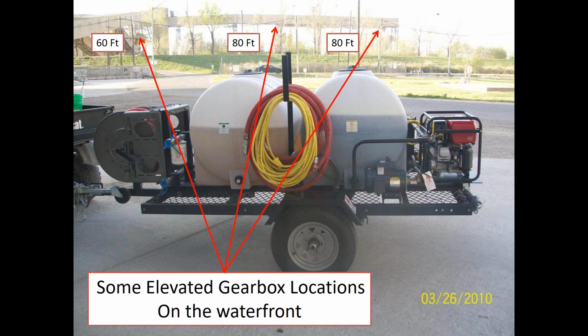This is a cart at a grain elevator. We built this trailer. It's got a dirty oil tank and a clean oil tank. It's got a little generator on the back with an electric pump. You can pump up to the top of bucket elevators and the top of high conveyors. We can change oil in those conveyors pretty easily with this little trailer you can pull around.